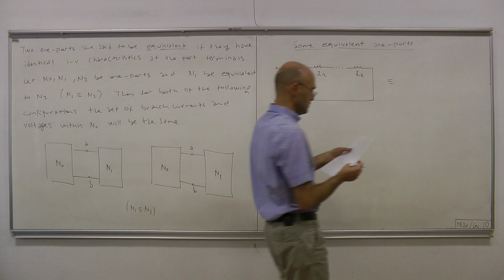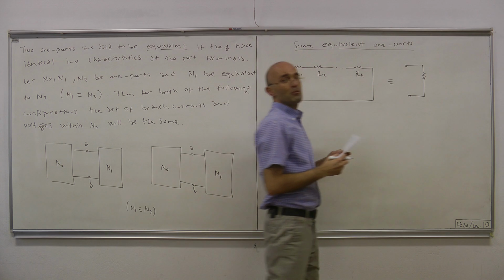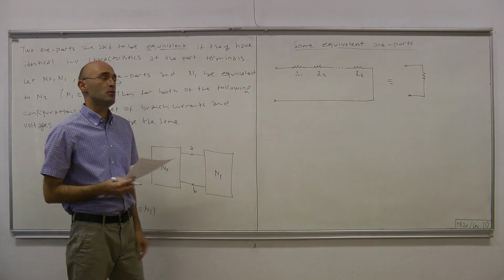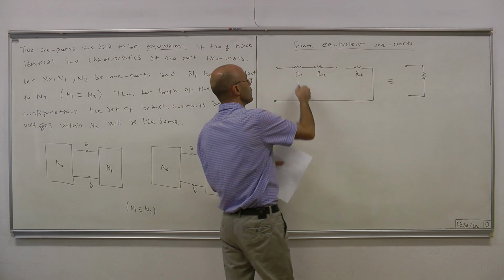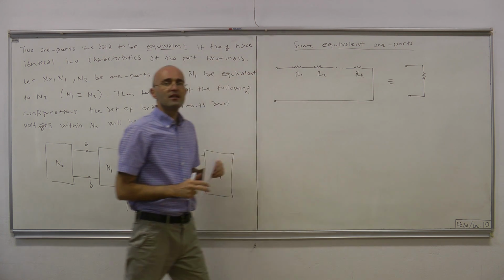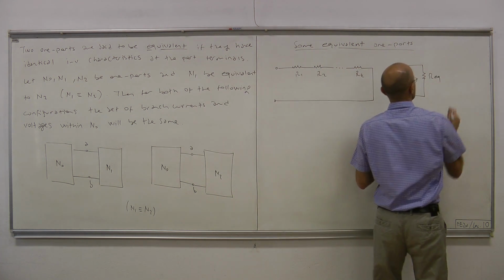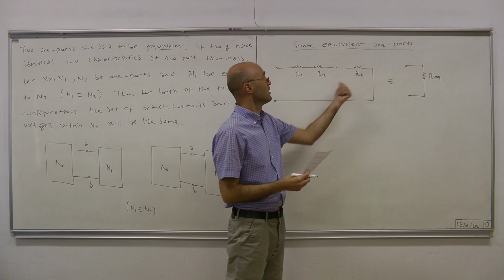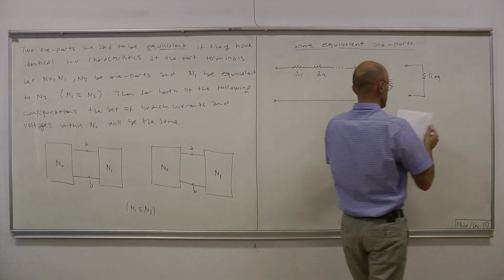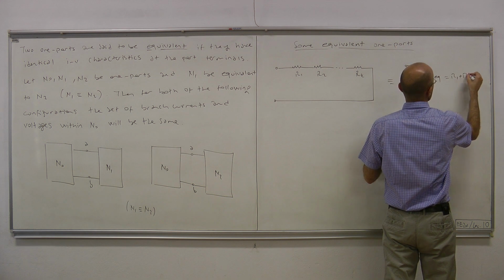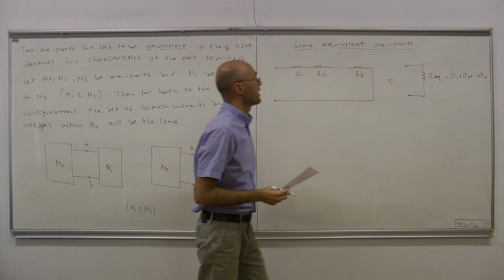So that's equivalent to a one port circuit with just a single resistor if the resistance of that resistor is chosen to equal the sum of those K resistances. Okay, they are equivalent. We're calling that resistance R effective, and that's R1 plus R2 plus up to RK.